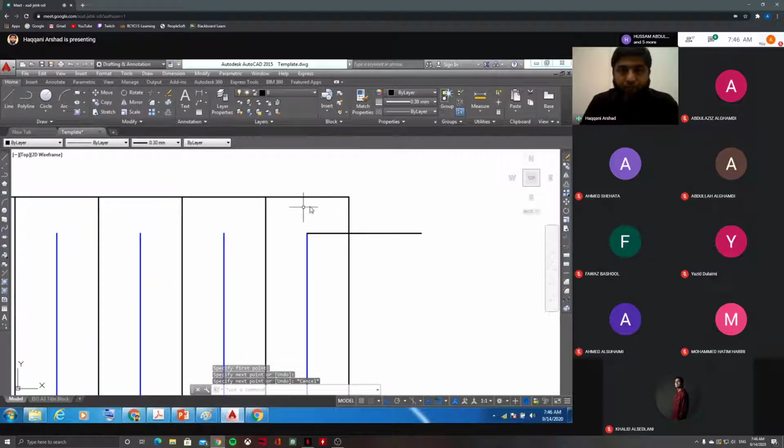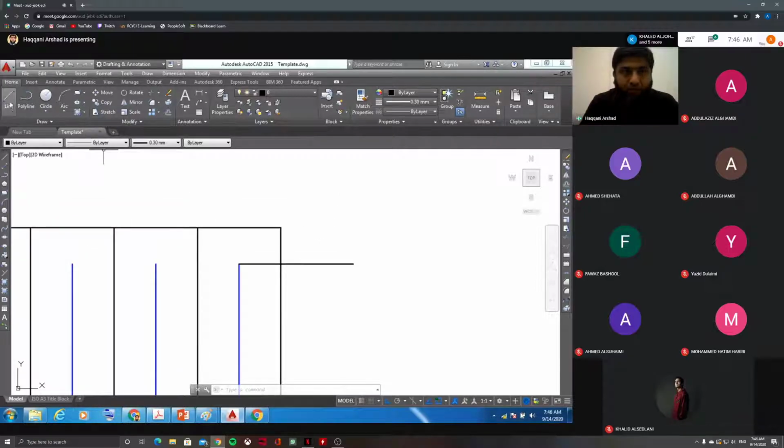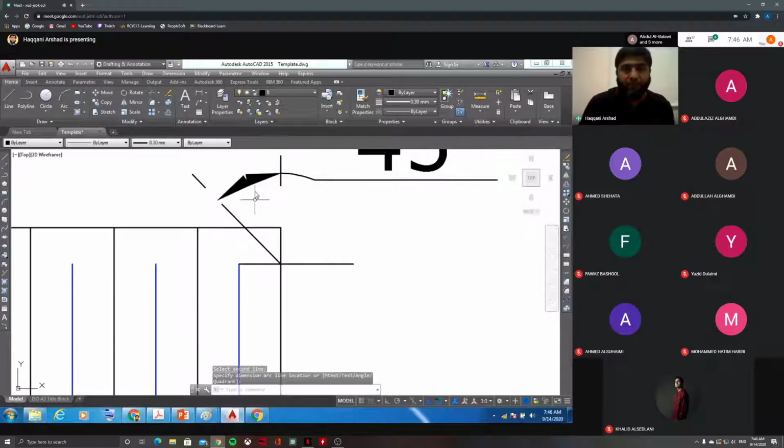You see here, a chamfer means a 45-degree angle. Always the chamfer angle will be 45. So what you need to do is connect from small d to capital D at an angle of 45 degrees. That will be a chamfer. I'm going to draw a line from small d touching capital D at an angle of 45. It will show you on the screen. So this is 90, 90 plus 45. How much? 135. That's like this. You can check the angle between this line, this is 45 degrees.